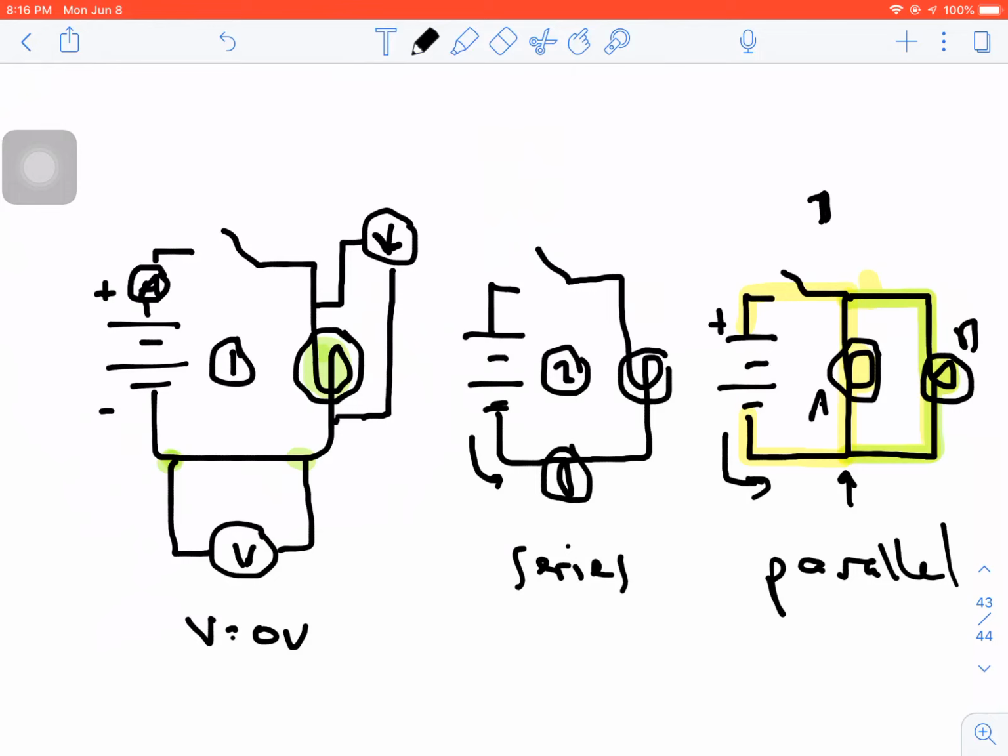They have to. They can't have any energy left when they get back to the source. So if I check the voltage here on either side of the bulb, I should find that the electrons had 3 volts down at the bottom, had 0 volts up at the top. So if I compare the two, the difference in voltage is 3 volts because they've used all of their energy.